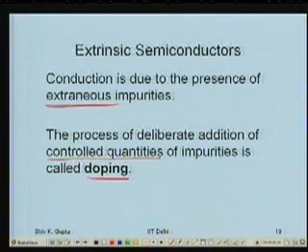And all the processes of diffusion we talked of are the ones which are exploited. Material is deposited on the surface, and then it is driven inside the material by heating, or you can put the semiconductor in a gaseous atmosphere through which you can allow the impurities to go in. You do this for a certain length of time at a given temperature to get a certain concentration of the impurity at a particular position in the solid. Okay? That process is called doping.